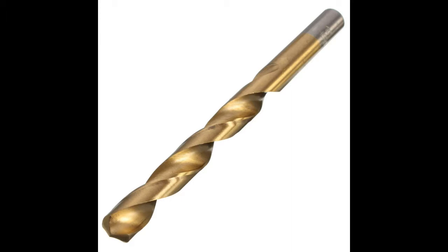130 degrees has become pretty common, and also different coatings. So the one in the image there has what's called a TiN coating on it, which is a thin coating of titanium to help cover the surface so that material doesn't stick to the drill. And that's very specific to the particular material you're going to be cutting. The drill you use in the lab may or may not have that coating on it, and for the purposes of this demonstration it's somewhat irrelevant.